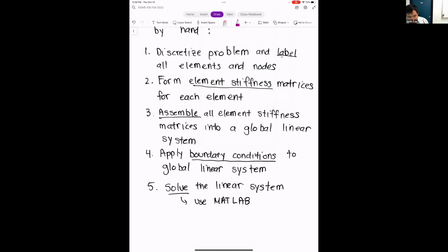Like I mentioned before, there are lots of different ways to apply FEA and lots of different ways to do it. ANSYS does not use the direct stiffness method, I will tell you right now. I've looked at a lot of FEA codes, in the guts of a bunch of research codes, and I'll tell you that the only thing that's different about FEA codes is step 2. Step 2, which is how we form the element stiffness matrix, is the primary difference, but everything else is more or less the same. For step 4, different people have different ways to do it, but they all do the same thing. But the main difference is in step 2.